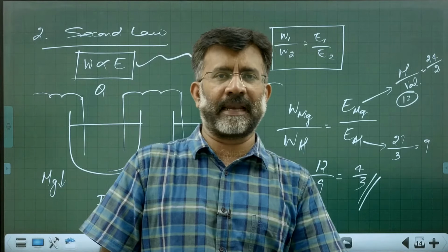A 38% solution of sulfuric acid is used as electrolyte. So in every cell when you learn, these are the points to be noted down. And see the anode reaction. At the anode, lead is oxidized to lead sulfate. At the cathode, what happens? Lead dioxide is reduced to lead sulfate.